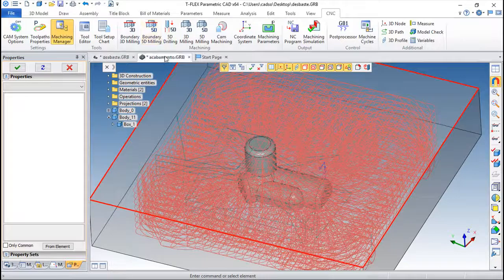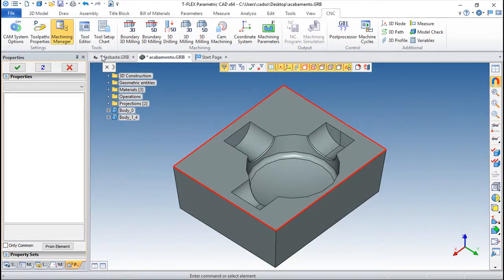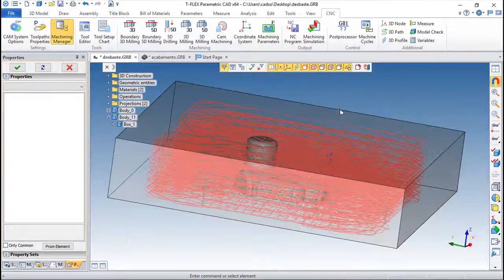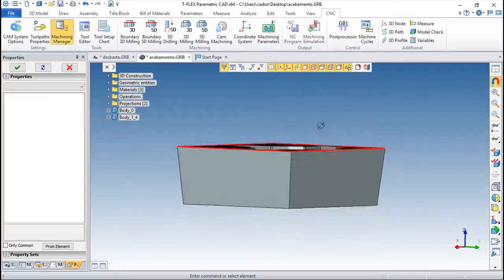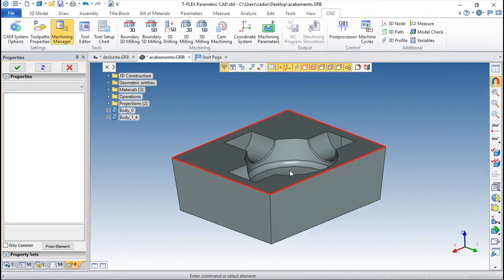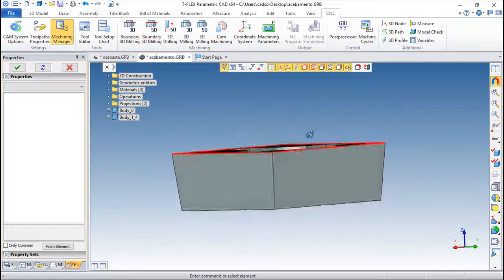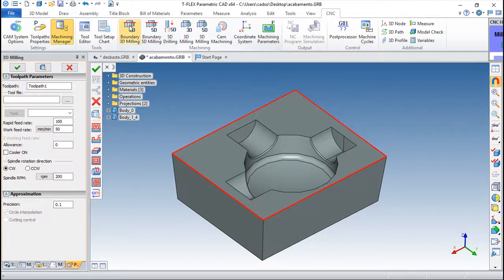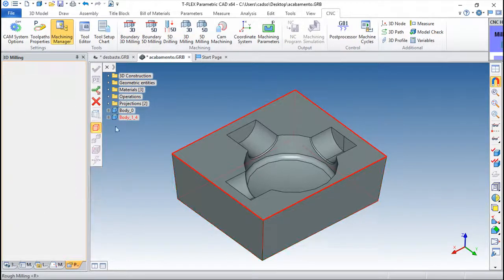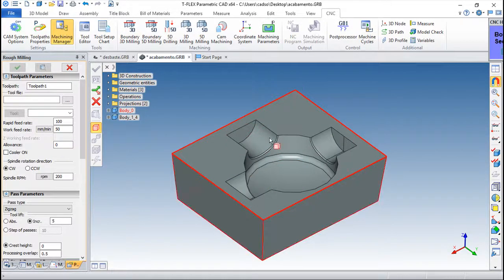Let us see the second file, which is a little different, and this is, as I mentioned, a convex shape. So we certainly would need to give this stock block a little above the part to be milled. In this particular case, in most of the cases, there is no need to give it above. It depends on what you have to start, but it's a different case once everything that is to be milled is below the top level of the part. So let us try to create a roughing toolpath also, and I have two parts, one on top of the other.